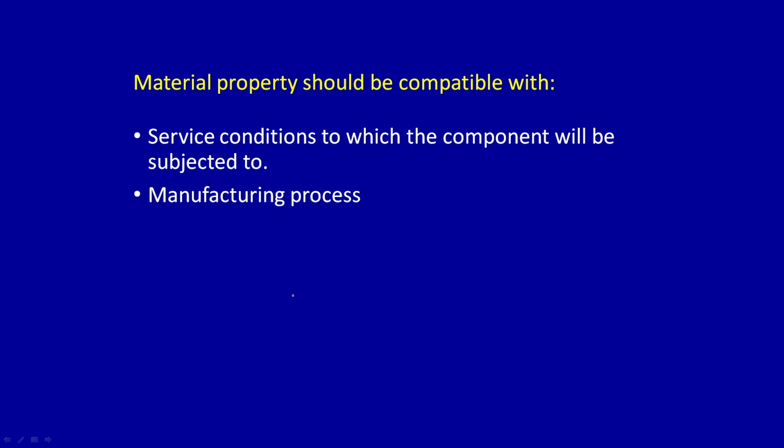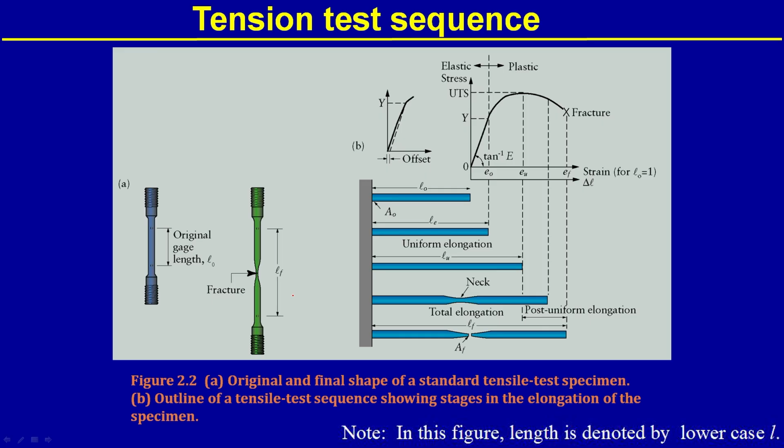Well, we talked about mechanical properties, especially we talked about tensile properties, because material can undergo a lot of different kinds of stress or loading, like tensile loading, compressive loading, shear loading. We talked about it a lot, but finally, I discussed only tensile testing, because that is the predominant testing method used in the world for ductile materials. For brittle materials, we use compression testing. Compression testing is exactly done in the same setup as a tensile testing machine, but loading directions are different.